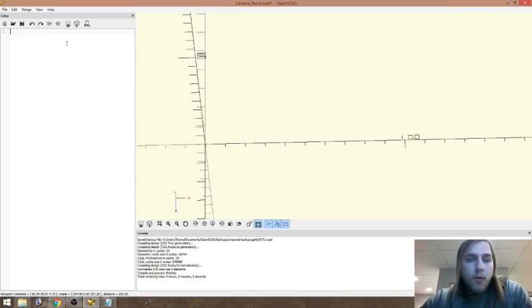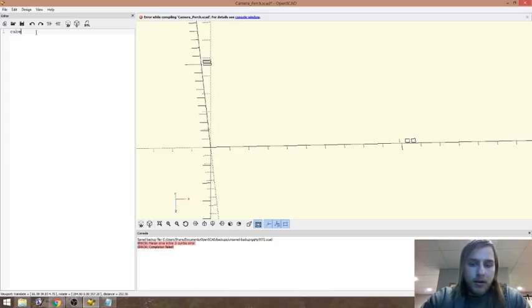So what we want to start with is just putting a simple extruded rectangle, and we do that by using the cube command. So let's put our cube. Like I said, this is very much like a programming language, so you have to make sure you get your syntax right, or you might not be able to render at all, or things may render incorrectly. So I've typed in cube, and this is for all the arguments, and the first argument is in these brackets,